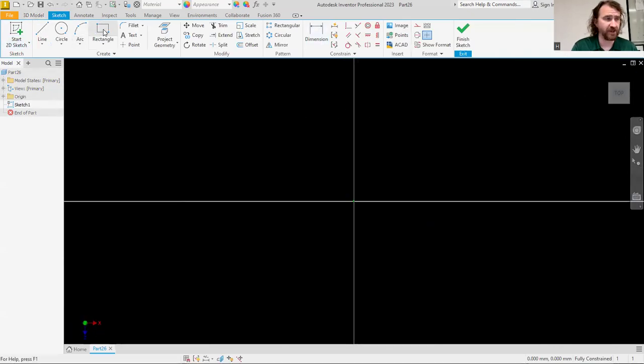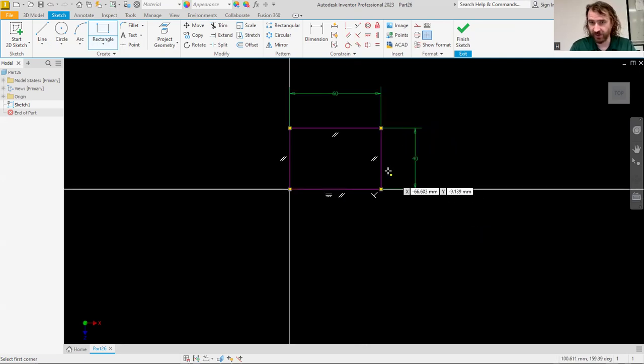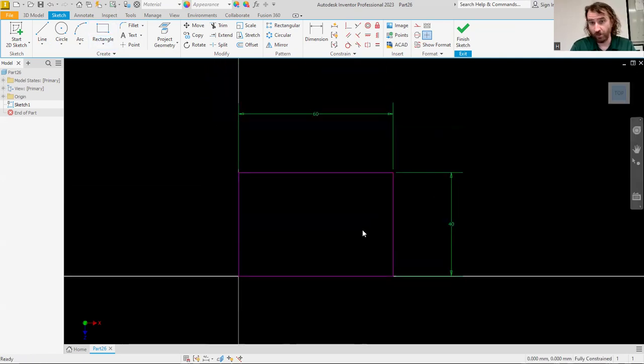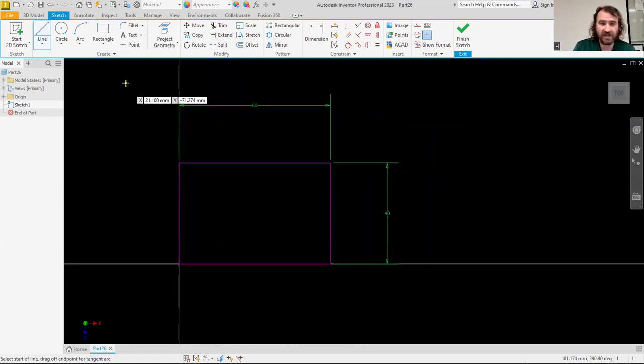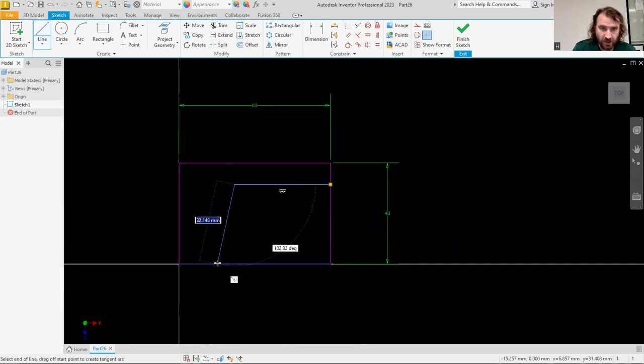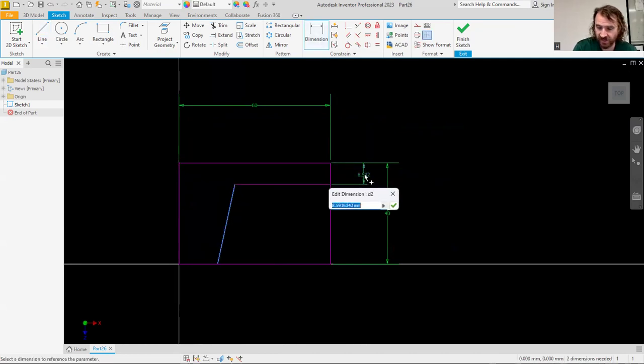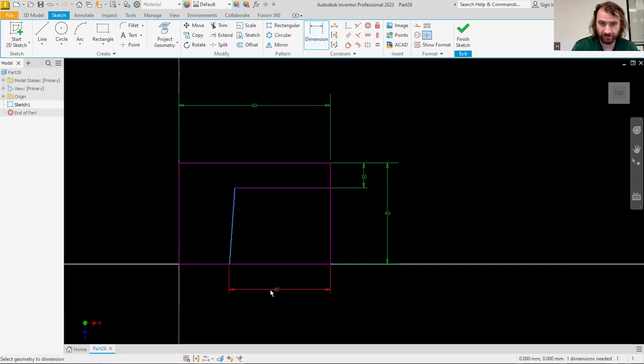There have been quite a lot of parts that we've been doing on the top view in this packet, that is for sure. So 60 millimeters by 40 millimeters gives us our base, our perimeter drawing here that we're going to be using. And now we need to just draw in the interior features of what is here. So this should be a 10 millimeter distance here. This from this line, this point to this point here, this is 40.